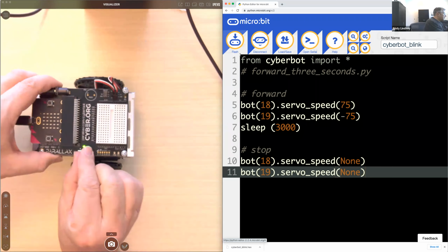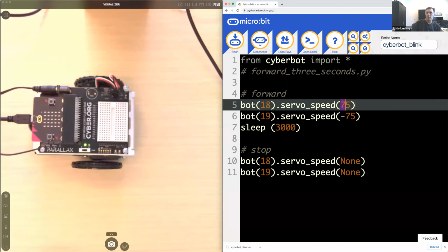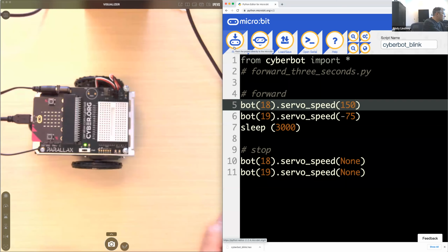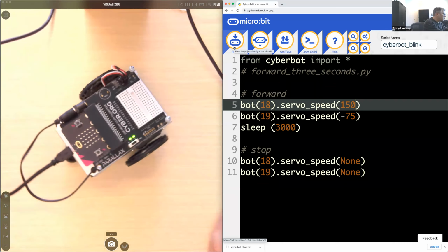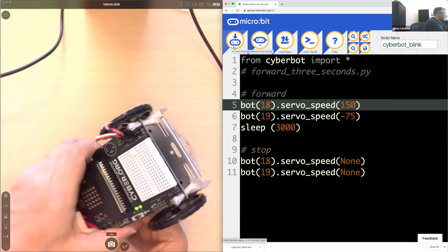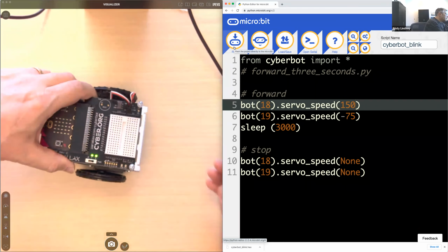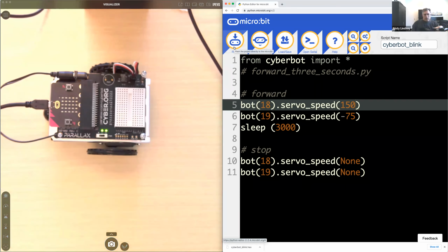Okay, that's very interesting, and it's way off calibration. So let's see here. That's the left servo. See if I give it a little bit more, tell it to turn really fast, what happens? Well, nothing, because I don't have the power in the right position. Okay, it seems like I managed to pick out a defective servo here. All right, I'll have to look at that later.